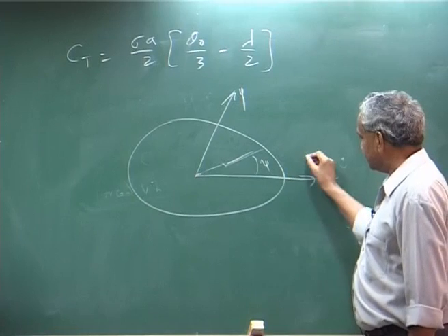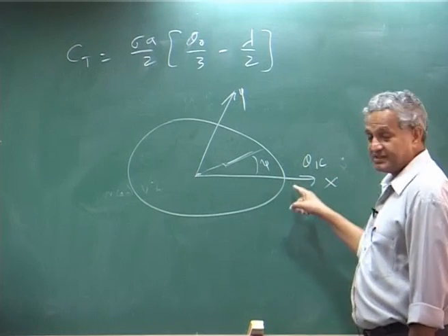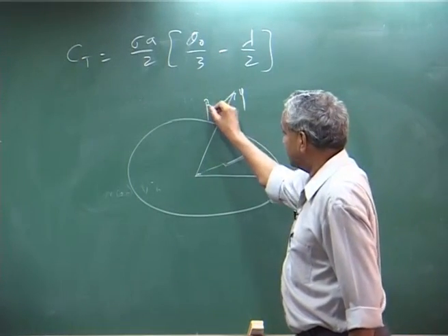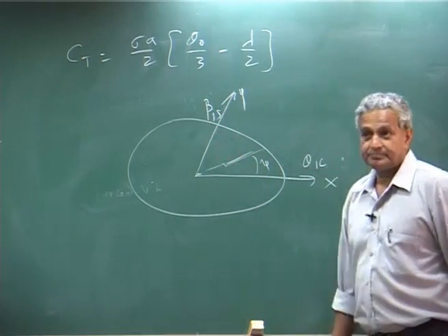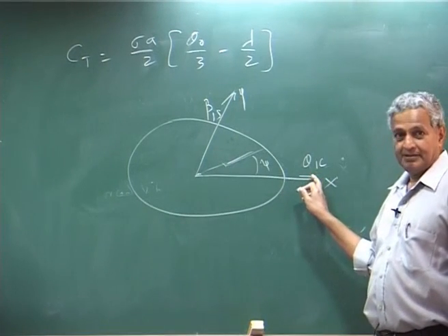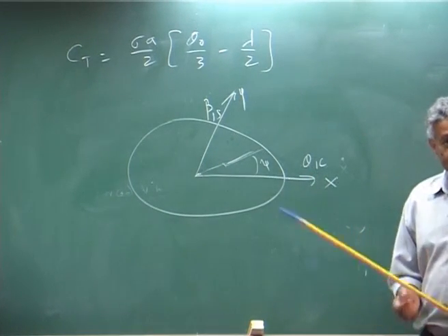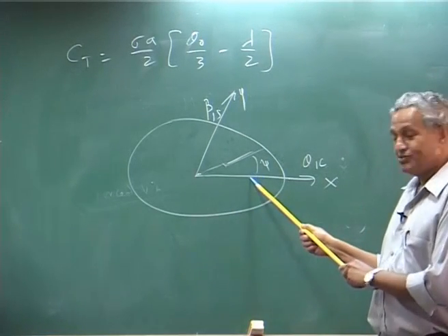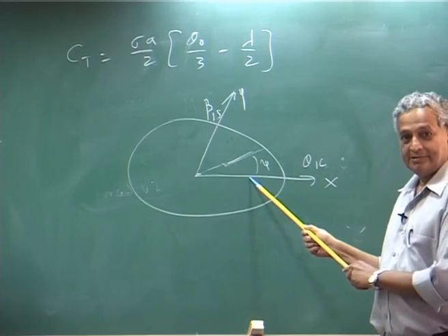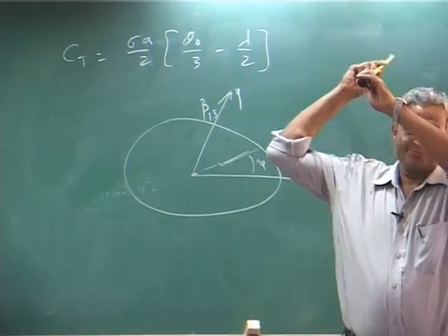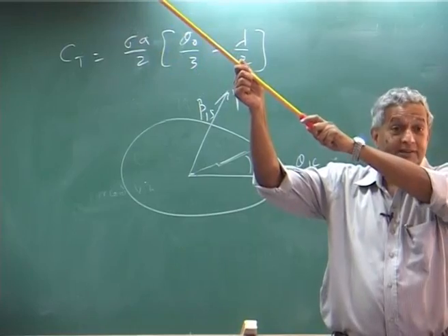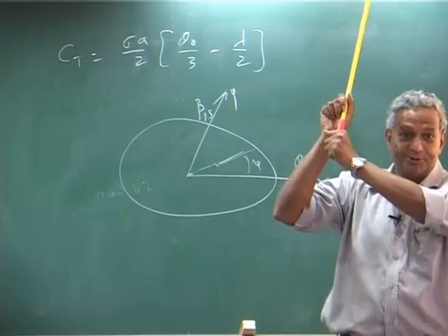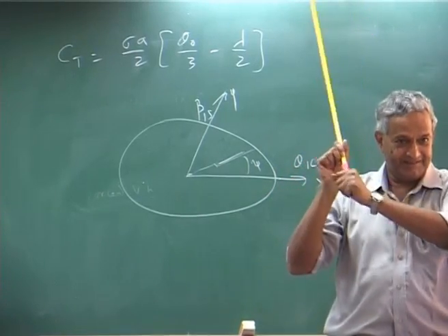If I change the pitch angle here, I get a response, because theta 1 C is pitch. If I increase my pitch angle when psi is 0, that means when the blade is here, the blade will flap up there, not that it will immediately go up, please understand.